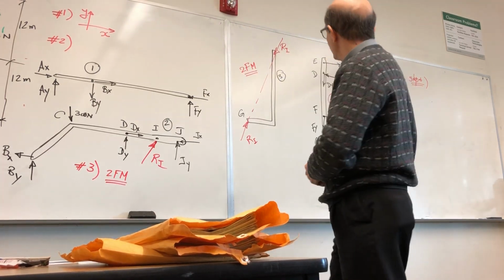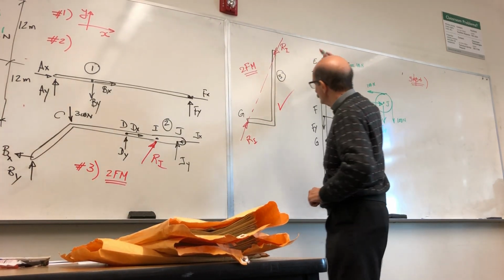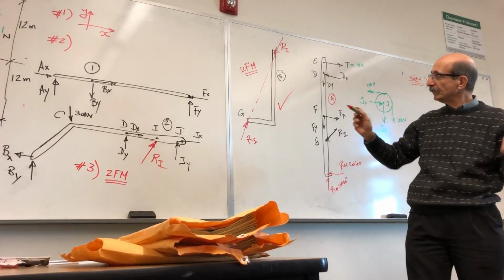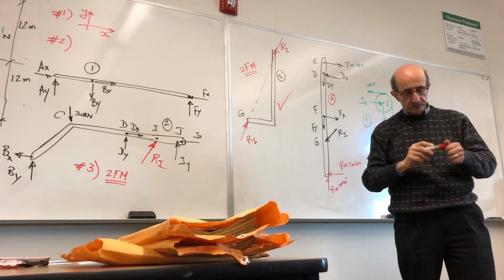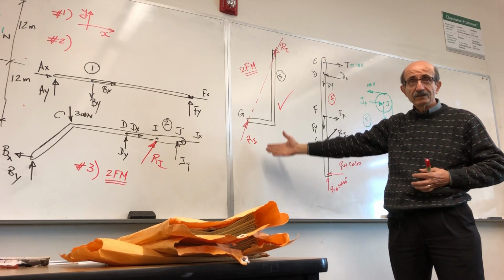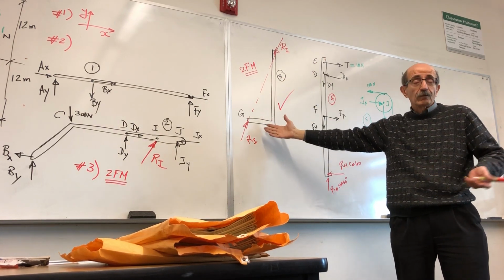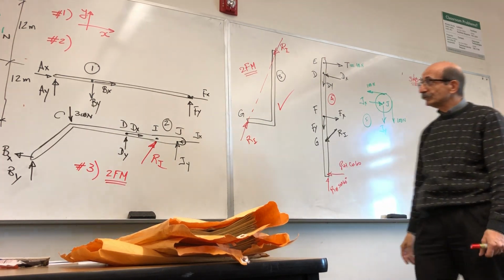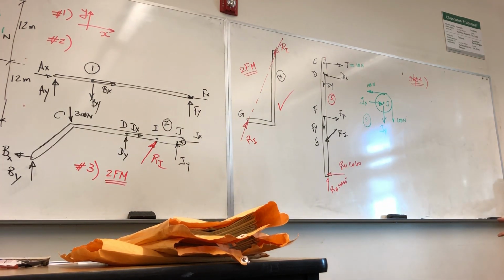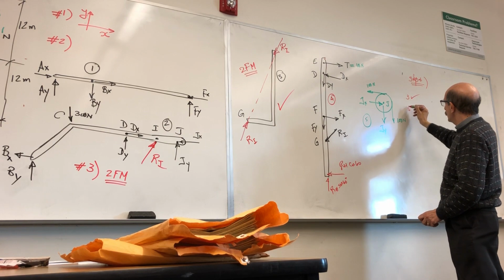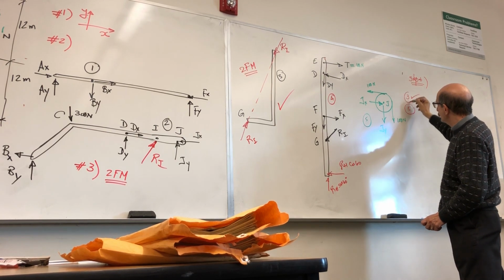So that I have already used. Any free body diagram you've already exhausted all your options on, put a check mark next to it, right? Because here you have only what? Equation, sum of forces along x and y equal to 0, which gives you those two being equal. So what free body diagram is next then? 5. So I would put here 3 already used. I'm going to start with 5.